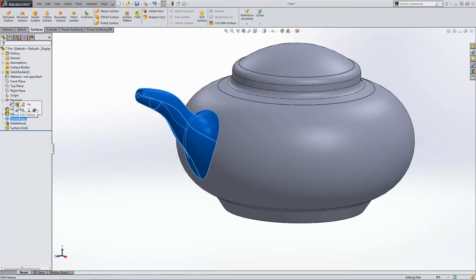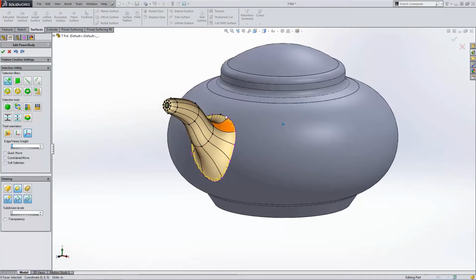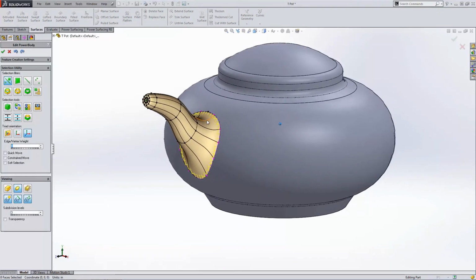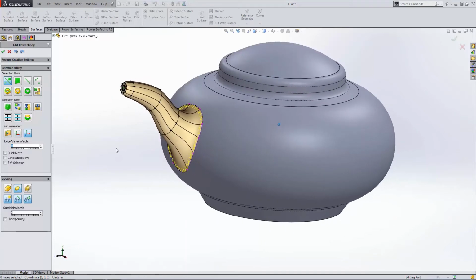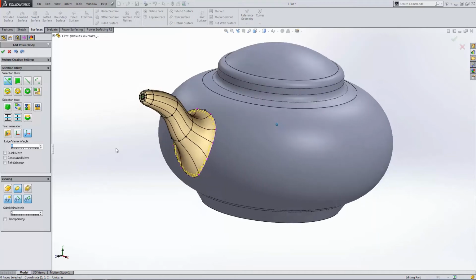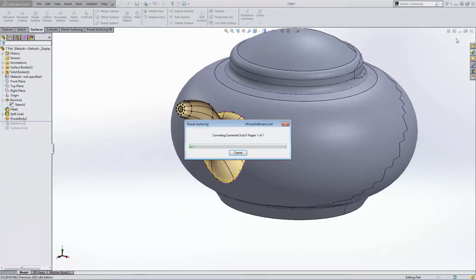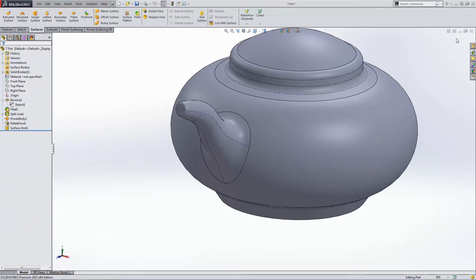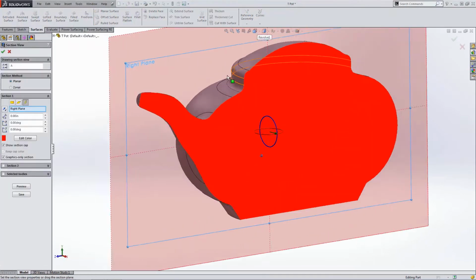functionality. The first of which is this teapot. Now we were able to import a reference that was a split face and attach our power body to it. Now this was originally a primitive, a cylinder, that I deleted an edge and then I had an open surface primitive. Now what I did was I constrained it to my existing SolidWorks geometry, and that allowed me to create the shape I needed and then still have the functionality that I can then delete a face on my SolidWorks solid part, knit these together, and end up with a solid body.